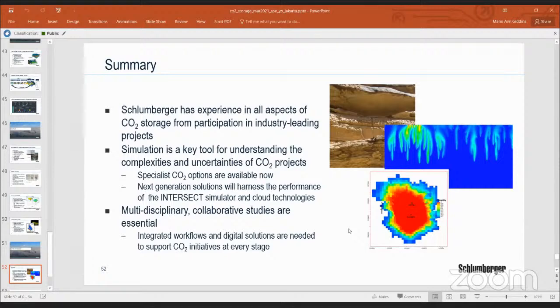However, we need to think about whether there's likely to be any corrosion, both what's the condition of the existing well as a result of operations performed so far, and also is there a risk that the metal that's been used in the completions will be corroded through CO2 operations and through the acidity of the water. So it's really something that has to be assessed again for individual fields.